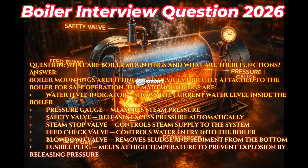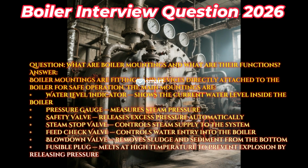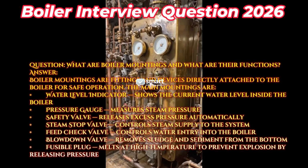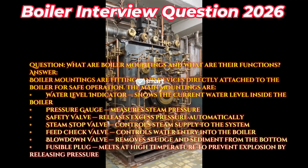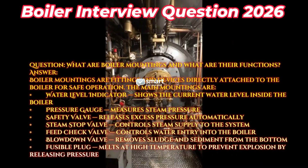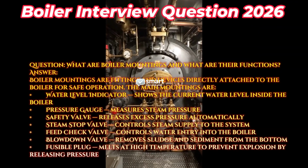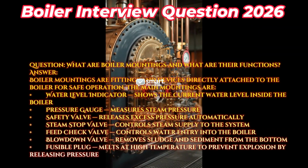Question: what are boiler mountings and what are their functions? Answer: boiler mountings are fittings and devices directly attached to the boiler for safe operation. The main mountings are: a water level indicator, shows the current water level inside the boiler. Pressure gauge measures steam pressure. Safety valve releases excess pressure automatically. The steam stop valve controls steam supply to the system.